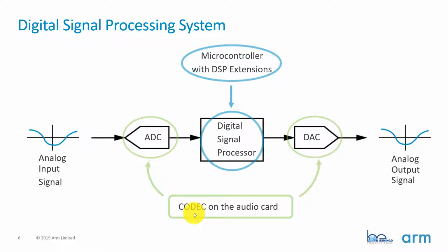You don't always need an external ADC or an external DAC. A lot of microcontrollers nowadays are actually very sophisticated. For example, if you use something like a PSoC 6 from Cypress, they have really good ADC capabilities on the microcontroller, and really good DAC control as well. So you might not even need external audio codec hardware in order to perform any type of digital signal processing.